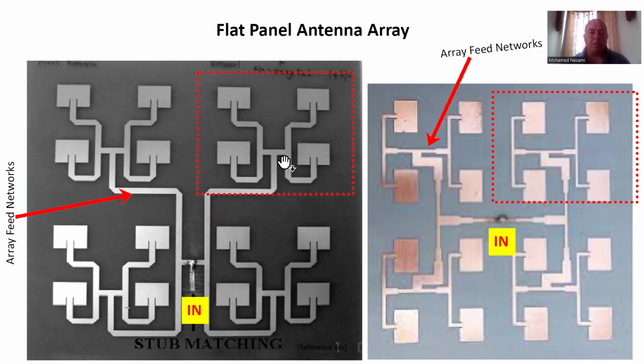In here, every T-junction has the same two widths on both of these lines, which means that this antenna array is actually excited or illuminated using a uniform amplitude distribution, meaning the power that excites each one of those elements is equal. Or roughly equal. Now, in this one here, you might see that this is actually using tapered distribution feeds, and we will get into that.